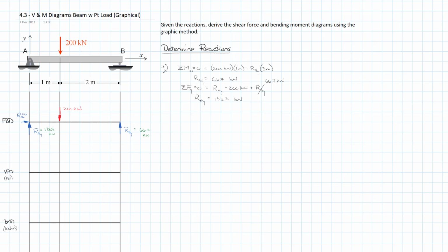Now, that being said, as important as that detailed method is, in most beam situations with fairly simplified loading, it's possible to use the graphical method, and the relationships between the free body diagram, the shear force diagram, and the bending moment diagram in order to very quickly draw the shear force and bending moment diagrams to get the information we need to go on and do other calculations. And so we want to have those skills. We want to build them up and be able to apply them fairly quickly so that we can be efficient in everything we do.